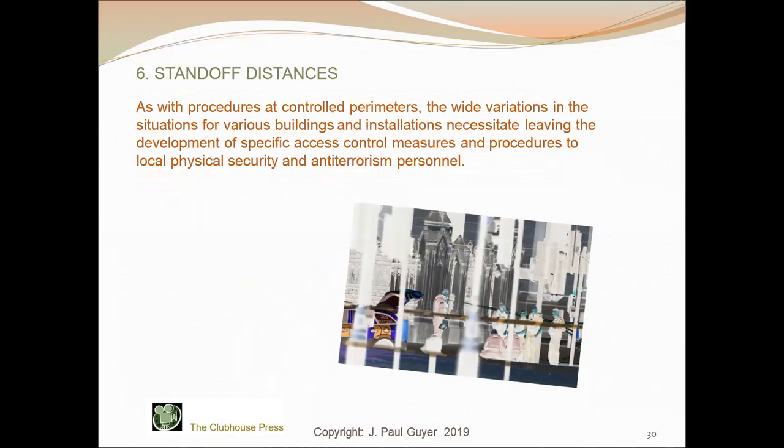These operational options allow for establishing access control for authorized parking at the applicable standoff distances in tables B1 and B2, in which case parking can be allowed to be as close as the minimum standoff distance to buildings without hardening or analysis. The access control in those situations must be established at distances in accordance with tables B1 and B2.